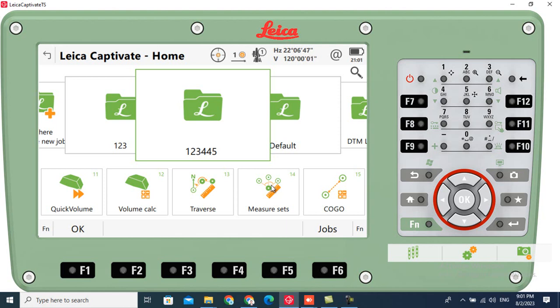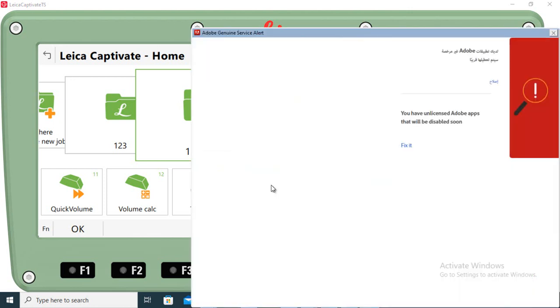Third usage of this application is making network adjustment. It looks like a traverse, but more precise. We stand on every point of the network and measure all the points we can see from this station or from this point, and we repeat this process for every point on the network. So we usually use this application if we need a precise or repeated measurement of the same points.